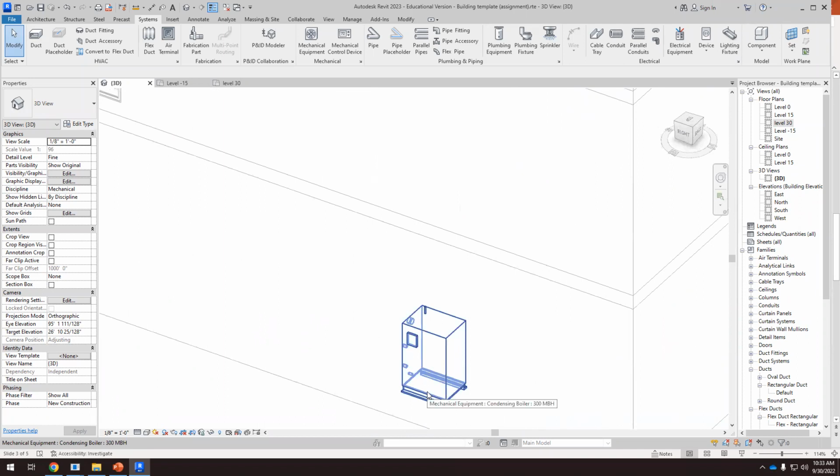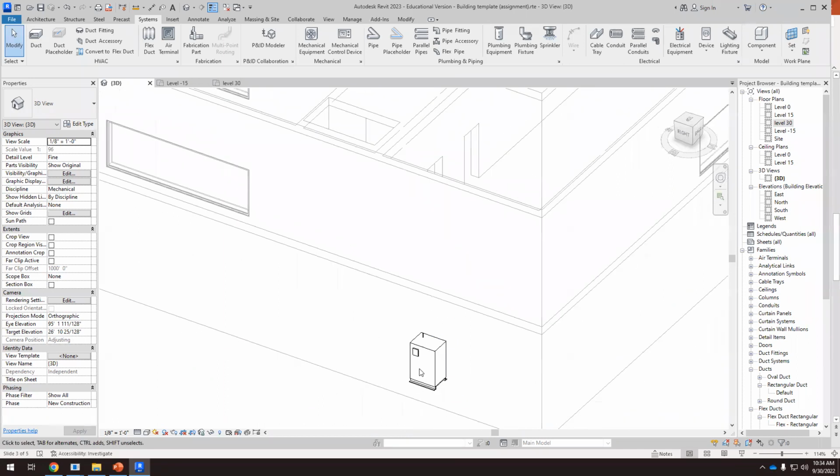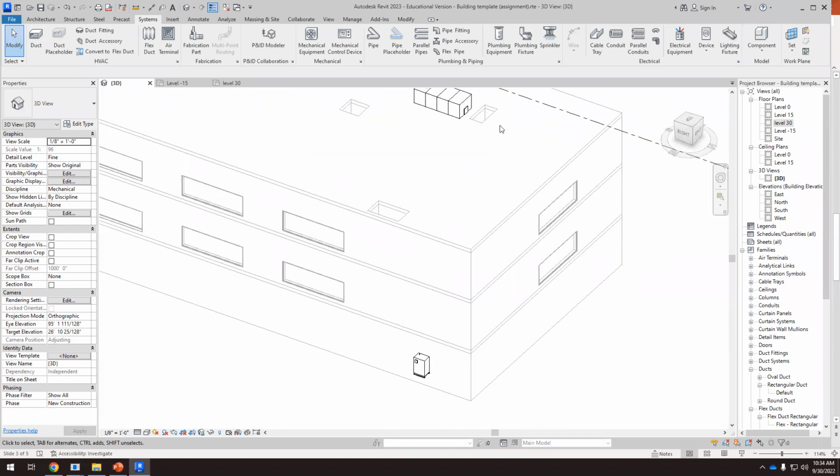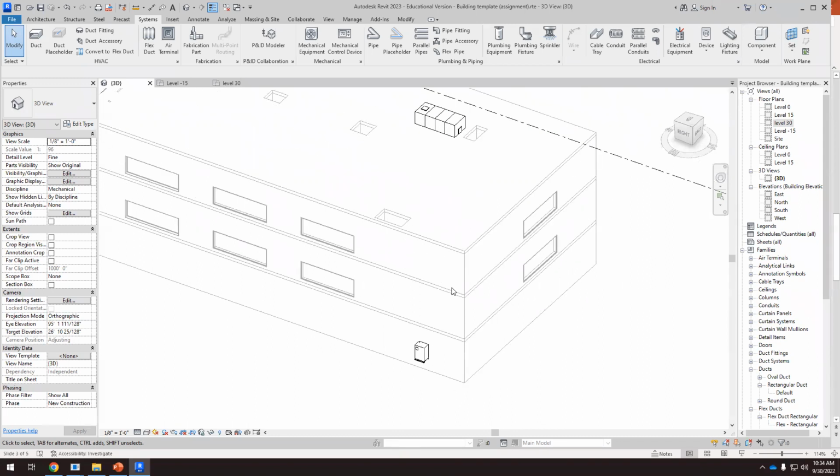We have spent money and energy on heating up this water, and suddenly it's out of the building and it's losing all that heat until it gets to the air handling unit. So we don't want that. And for sure, we need to use thermal insulation, but the fewer pipes outdoors, the better.